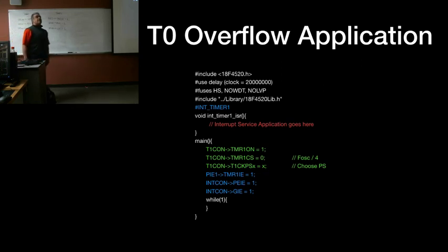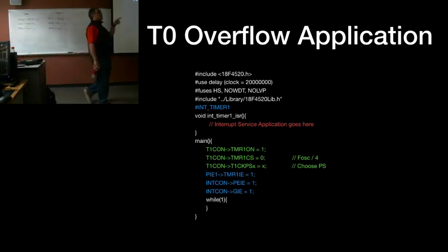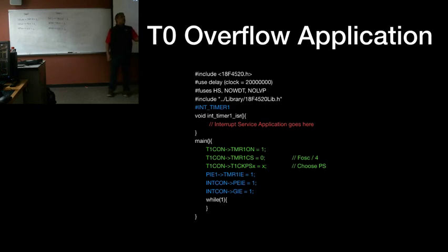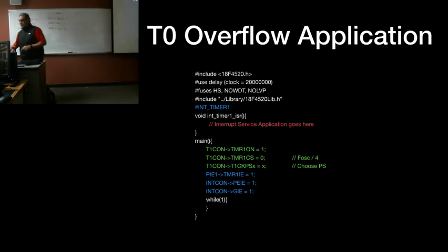After you're done, you're going to have timer 1 going around in one of them, and timer 0 going in a different one. So you could try to do this in timer on pin C1, let's say. And this just is truly copy-paste. There's nothing special about it. You just type those lines exactly like that, and you put an output toggle right here in the middle, and the system will just work. Right? So that's what I want you to do. Let's spend some time doing this. So here we go. Let's do this.